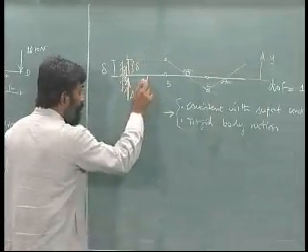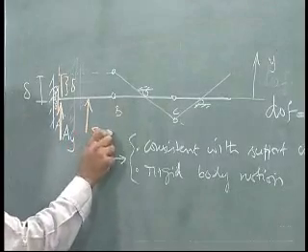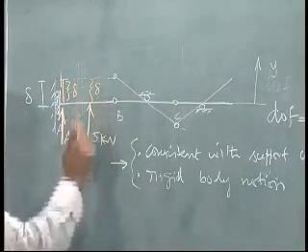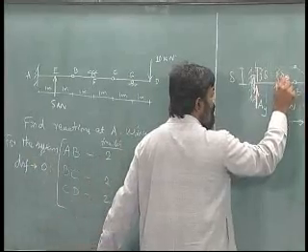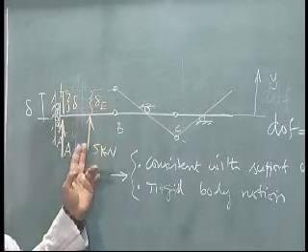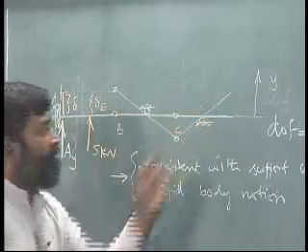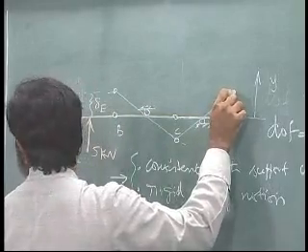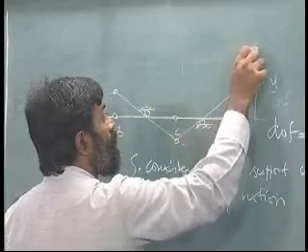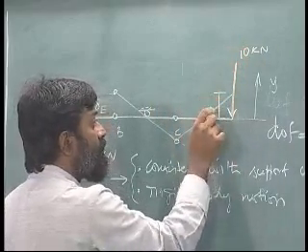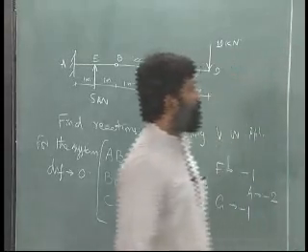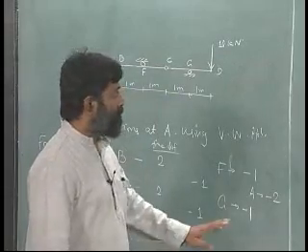There is a 5 kilonewton applied here, and this is the virtual displacement, which I will represent as delta E. I have to write delta E in terms of delta if I have to solve for this. Do I need to draw anything else? Only here. Here I have a vertical force acting like this equal to 10 kilonewton, and this is the virtual displacement delta D. Is this clear?